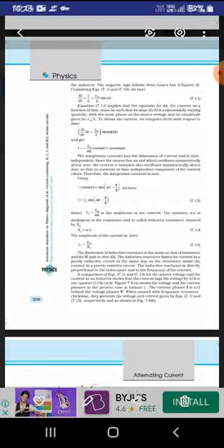Let's take, and also we will put Vm/L, we will integrate it, then di/dt is Vm/L, and therefore i is equal to minus Vm/WL cos Wt plus a constant. Here we will put cos Wt equal to sin(Wt minus pi/2). So when we solve the whole thing, the amplitude of the current is Im equal to Vm by XL.